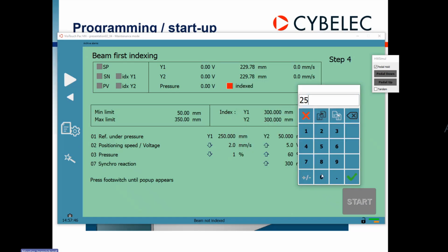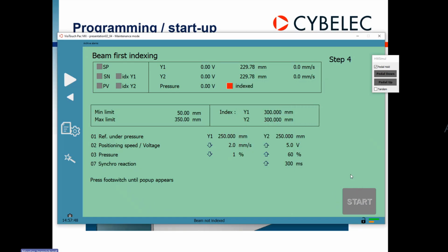And why do we do this? It's because we want to know precisely where the beam is. So we put the beam on the blocks. And then once the beam is detected as not moving anymore because it can't go any further mechanically, it's on the blocks, it's stuck, then it will teach this value on the encoder. And then when it indexes, it will get the index pulse. So we will see this value change.